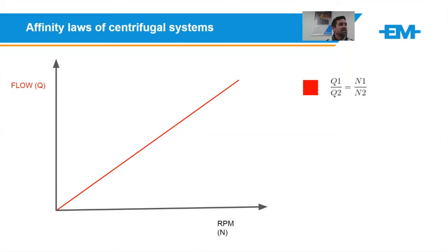I see there's another question. I'll just park it here. On your smaller Delta drives in the range of 2.2 kilowatts, how can I get drive settings off if the front pad screen is damaged? Good question. Like mentioned before, all the drives have built-in Modbus, RS485. Depending on the drive model, there's normally an RJ45 socket on the drive. That is the socket that has the Modbus terminals in it.